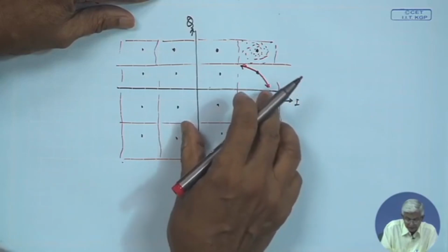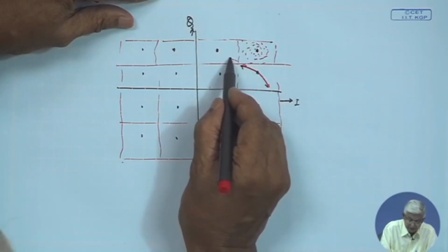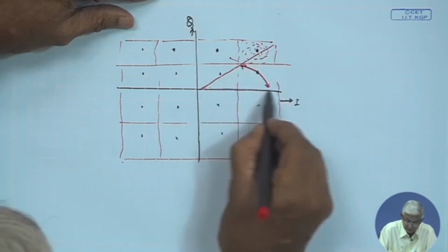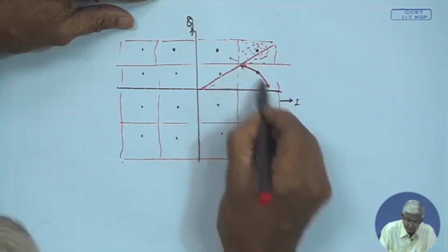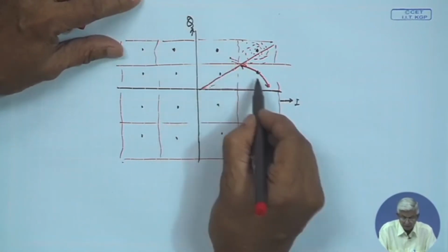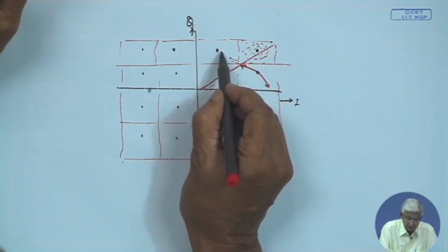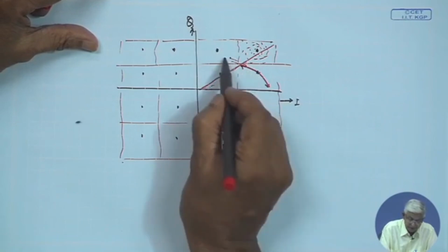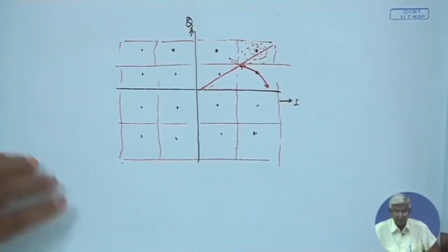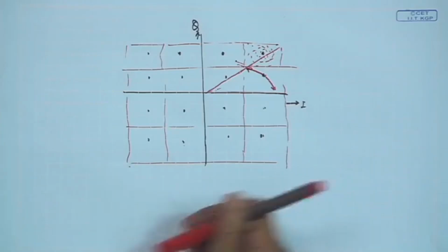So, because of the phase nonlinearity, the constellation may change, and your vector will go into the other decision level, so that a wrong decision is taken. This is, let us say, the decision boundary for this particular vector. Now, if it changes more than the decision boundary, then it will be detected as a wrong symbol. Let us say it was 0101, and this symbol is 0110, and so this will be detected wrongly when it crosses this. This is another effect of the constellation tilt due to intermodulation, and this increases the BER.